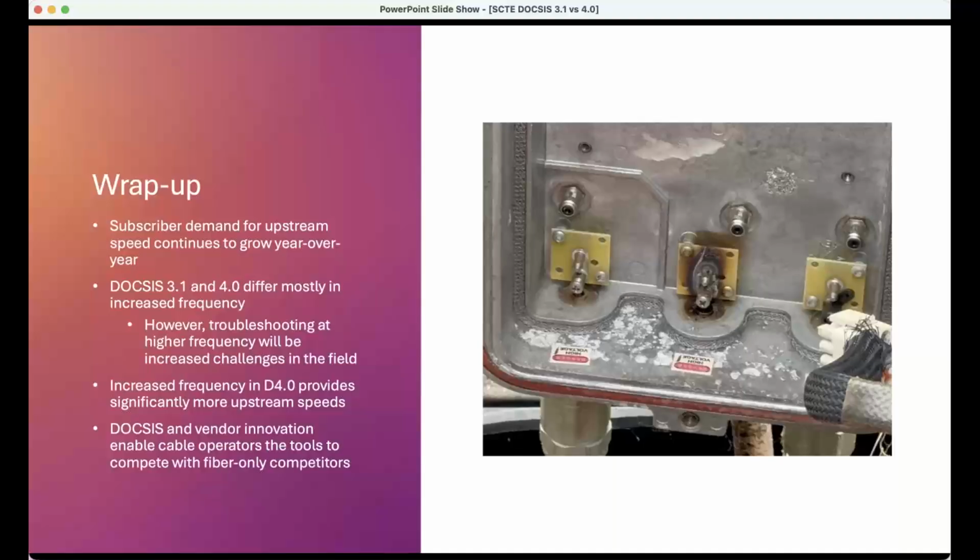The modem and the CMTS will negotiate back and forth, and let's say that there's no impairments between the modem and the CMTS. The modem will use 4096 QAM because no impairments. Now something happens in the cable plant and an impairment will arise, and that modem will see the impairment. The modem will drop down and see, well, let me see if I can use 1024 QAM.